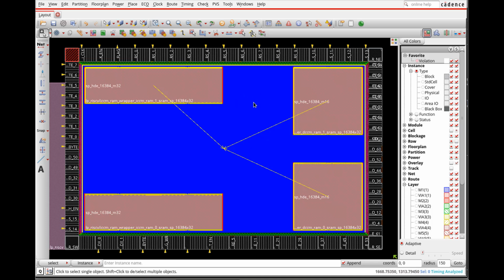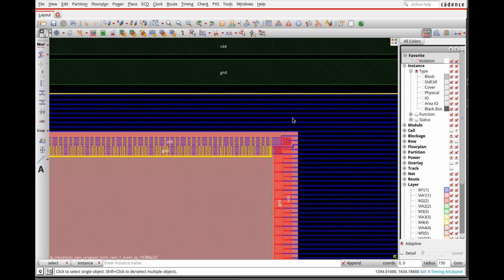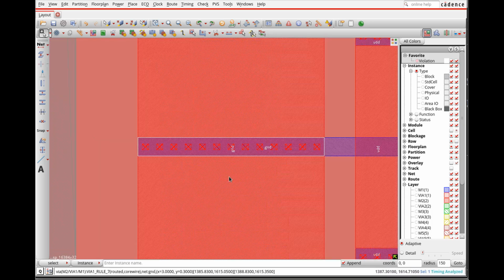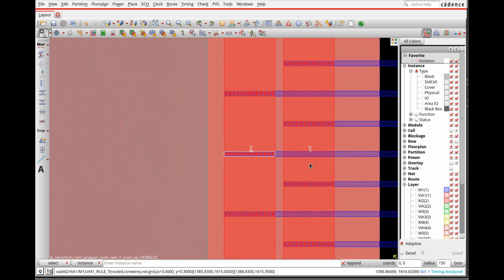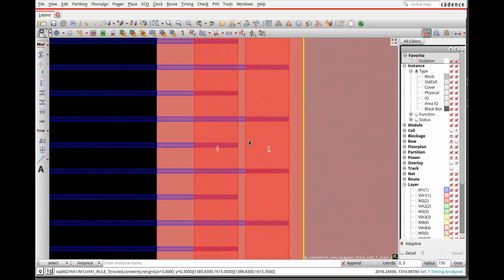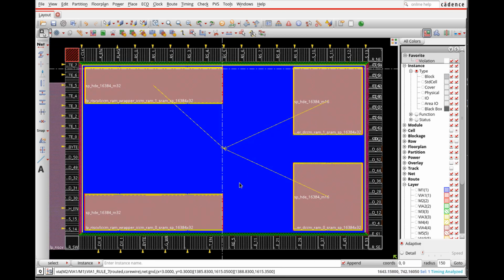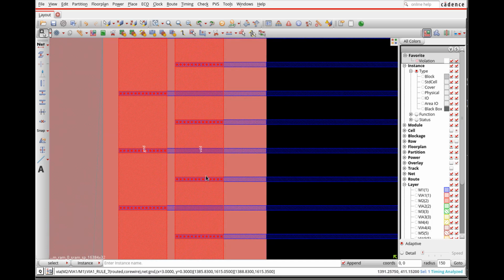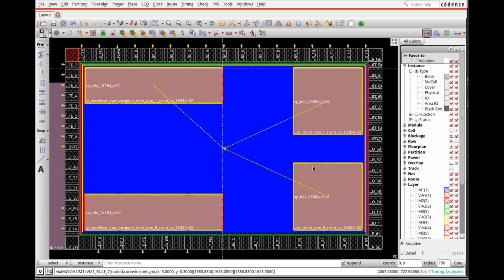And what do we see happen? We have all this blue. Blue is metal 1. I can zoom in over here, and I see that I got these core pins, and you see that this core pin is ground. Okay, and it is connected over here with nice vias to the metal 2 on this layer over here. And I see that it's really nice to terminate these with these rings that I have over here. They terminate very beautifully and probably don't cause any DRCs. So that's why I also like to use these rings, even though they do waste quite a bit of area.